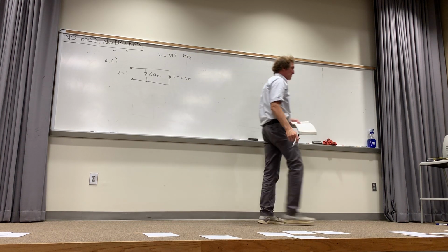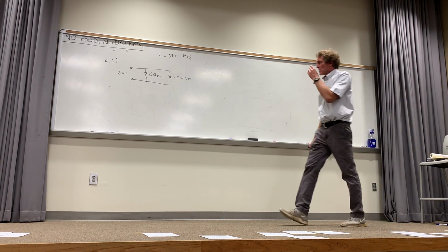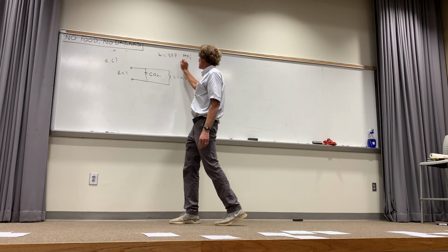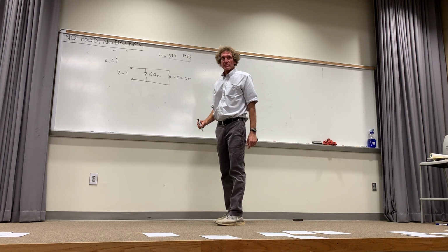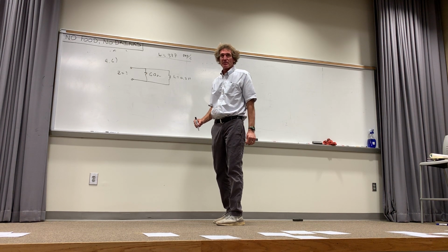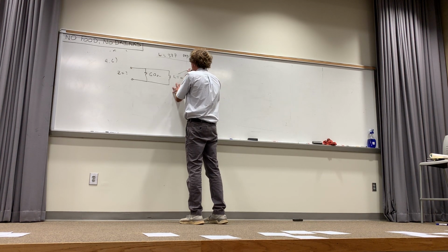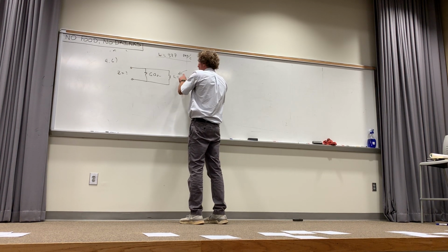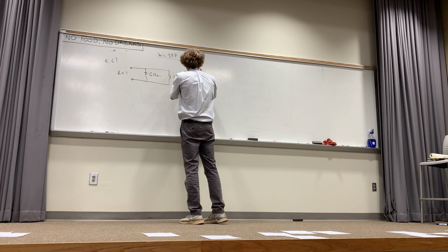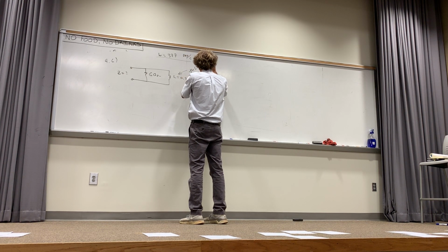We'll do this one. This is going to be an easy one. Now, I'm going to tell you, this gives us a frequency, right? That's 2 pi times 60 hertz actually. It's 120 pi, 377, roughly. So what do we replace the inductor with? It would be replaced with J omega L, or J 377 times 0.2.